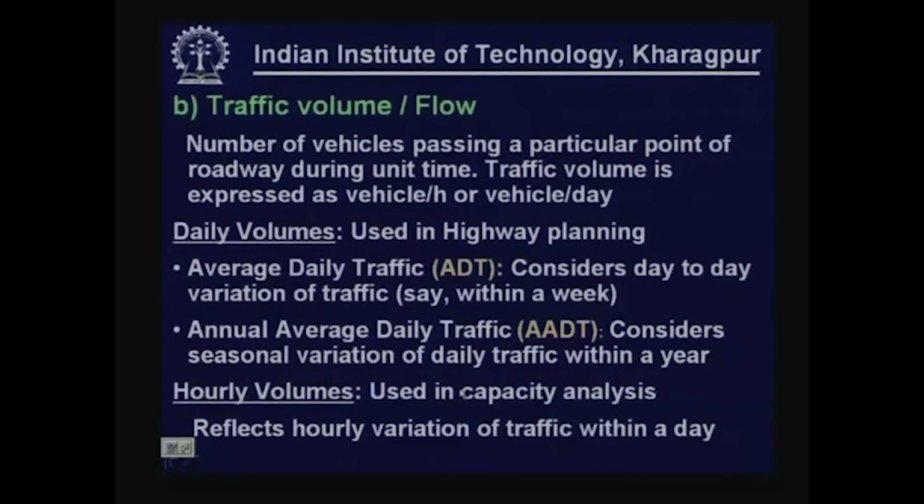Now, traffic volume we measure normally in terms of number of vehicles passing a particular point of roadway during unit time, and traffic volume is normally expressed in terms of vehicles per hour or vehicles per day. We express traffic volume in terms of daily volumes, which is normally used in highway planning. Two types of measurements are normally used for representing the daily volume.